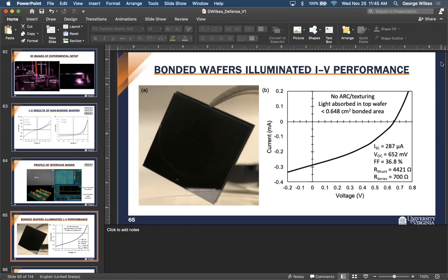Okay. Yeah, but I didn't quantify the force that it was pushed between the two. Did you check the surface condition? Obviously these are just centimeter-sized wafer pieces that you put together. Did you check how planar those surfaces are to each other? You mentioned air gaps, so I'm wondering, sometimes you have to work with wafer bow and all these things. Was that an issue here?